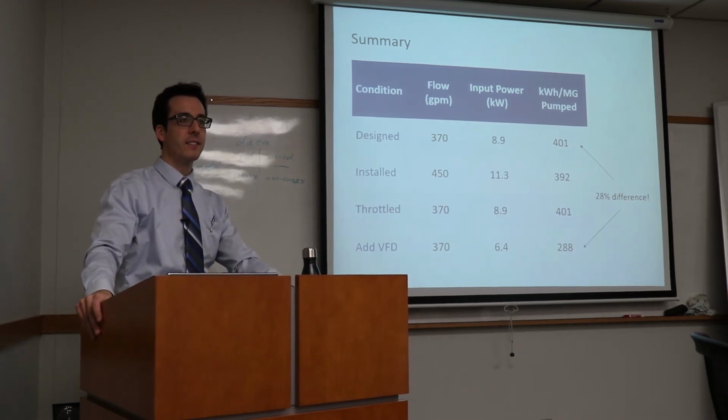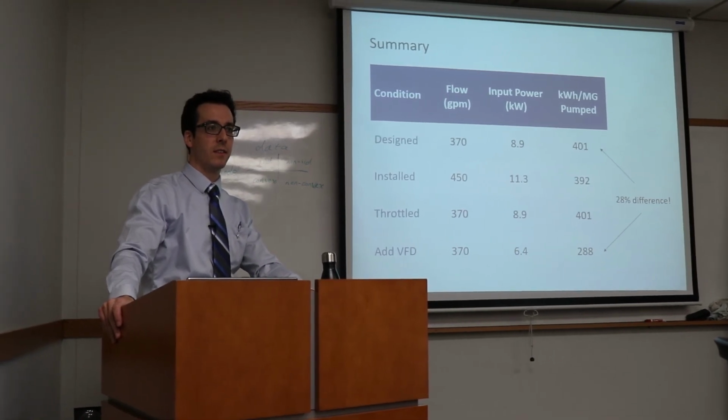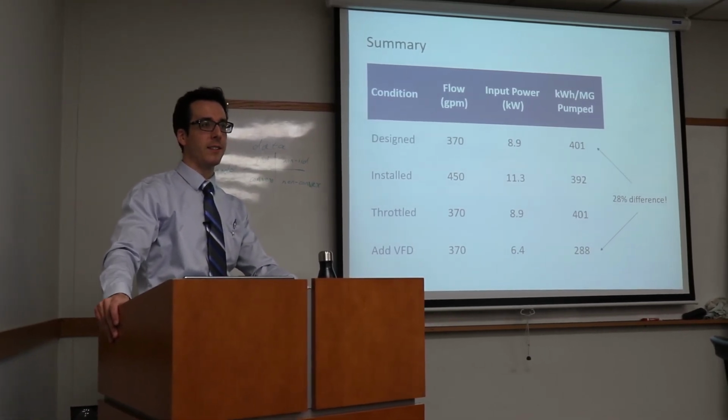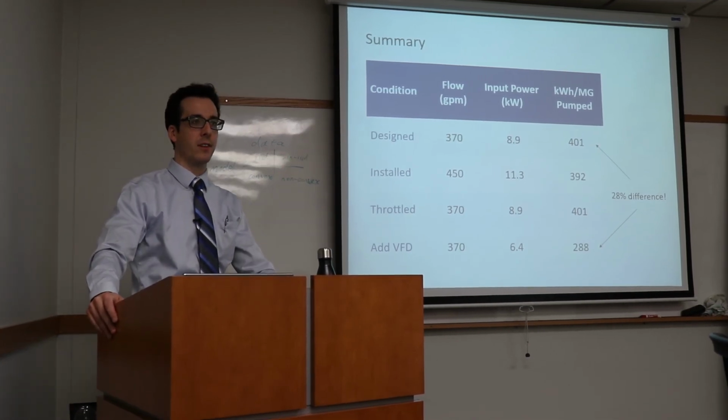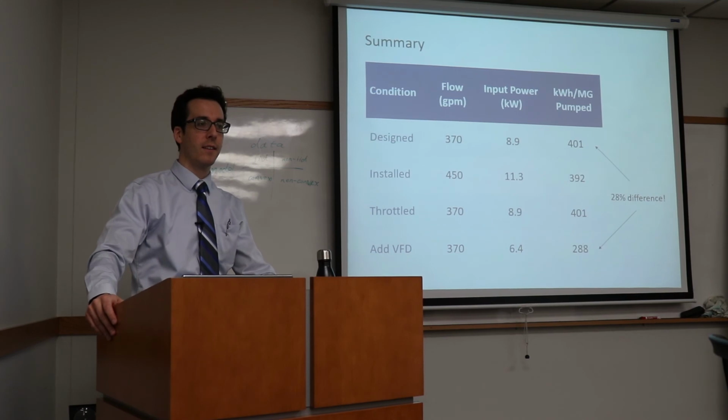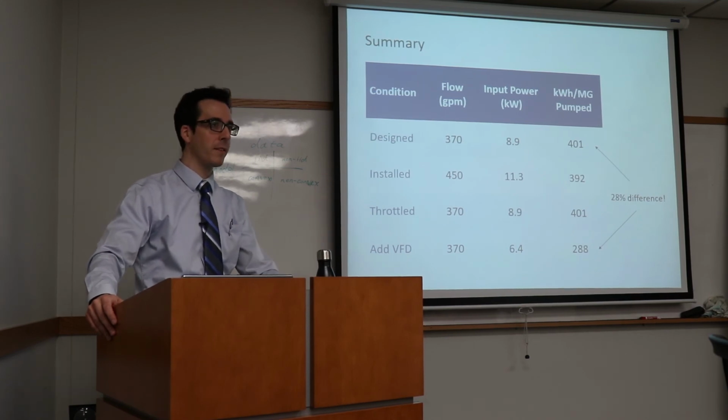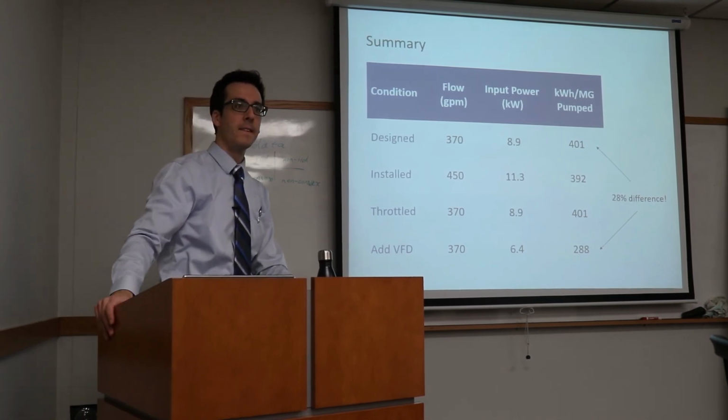How do you go about getting those alternate pump curves for the VFD? Yeah, you can get those from the manufacturer. What pump curve corresponds to certain VFD speeds, and it'll often show up on the pump curve.